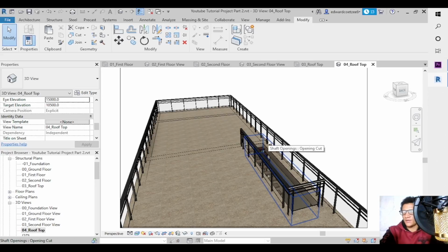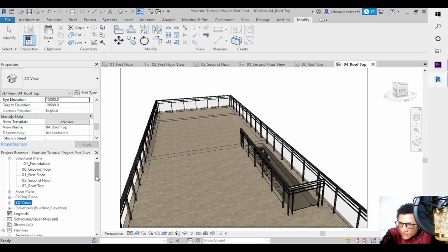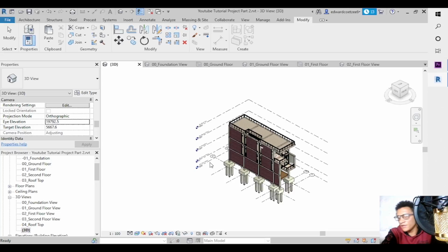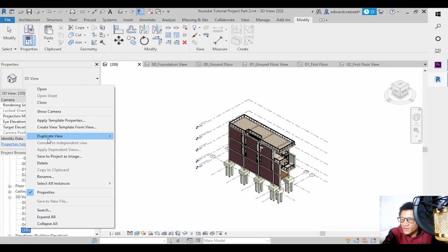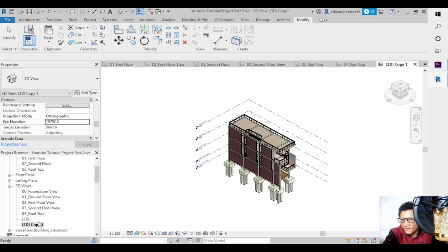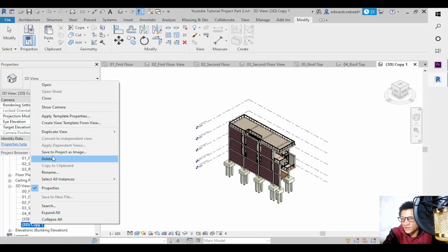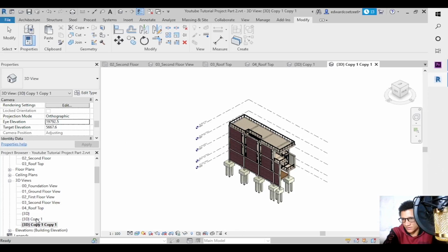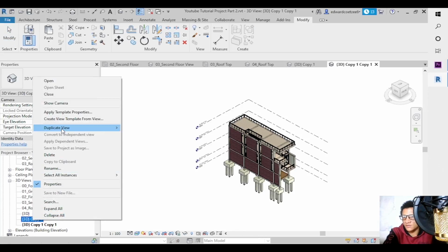And when you are done with that, and basically everything is organized there, you have your 3D view as well. With your 3D view, you can copy this and duplicate with details. You basically want to do that twice, duplicate the details. Now one you want to call the structural, let's just rename this.